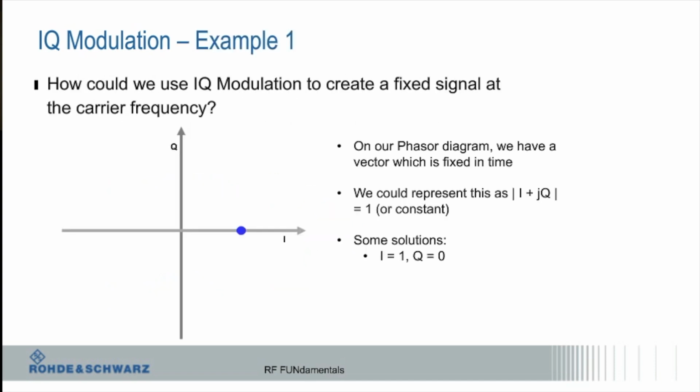The IQ modulator enables simultaneous amplitude and phase modulation. So I'm doing amplitude and phase together. In the simplest case, if I'm doing BPSK or QPSK, there's no amplitude component, but then I can add an amplitude component very easily.